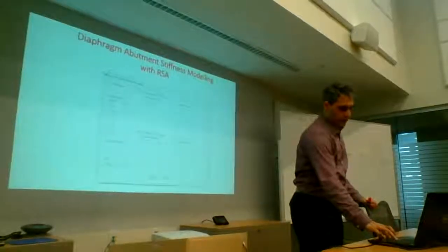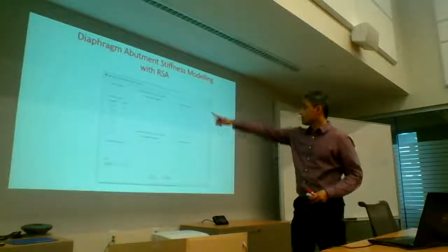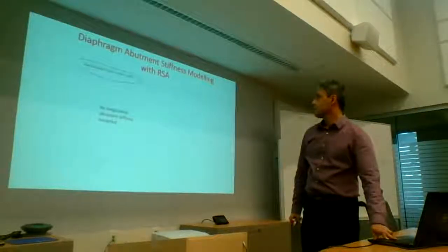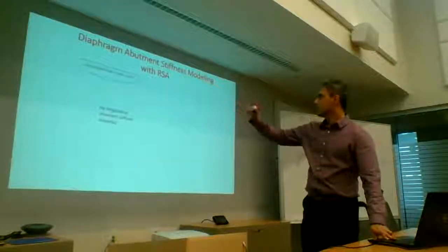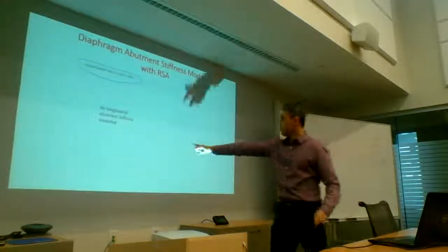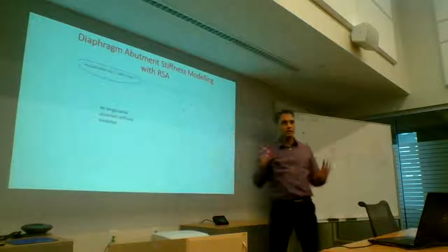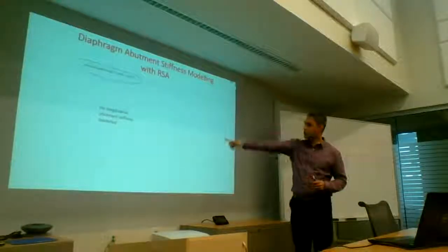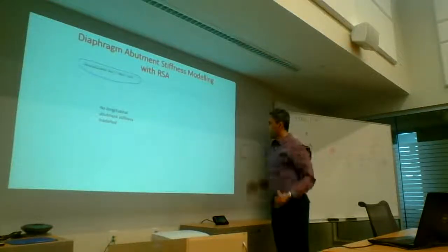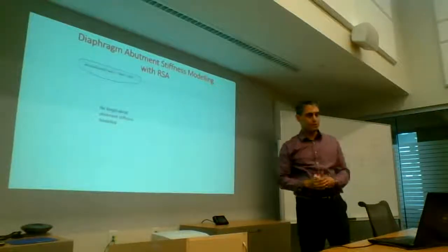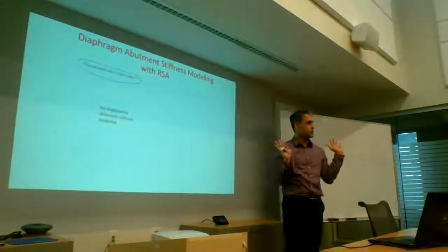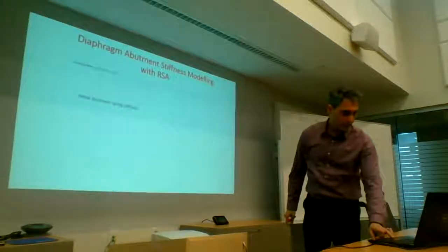So very quickly, I'll show you, here's my abutment stiffness. I've put 4,300 as a starting point. So here we start, okay? No longitudinal abutment stiffness model. I've got all the stiffness just coming from my bent. I've put rollers at the ends. Well, guess what? My period is 2.6 seconds, because this is like a 100 meters or plus bridge, long bridge. And all it's got is 2 columns bending in single curvature. That's all my stiffness.